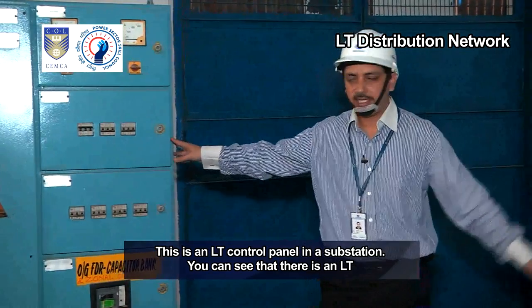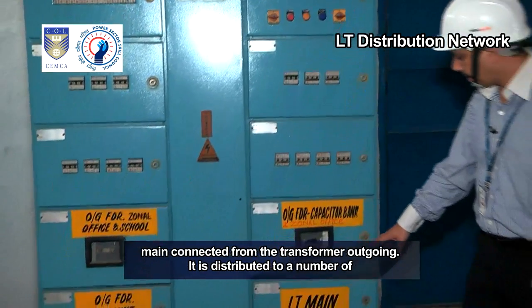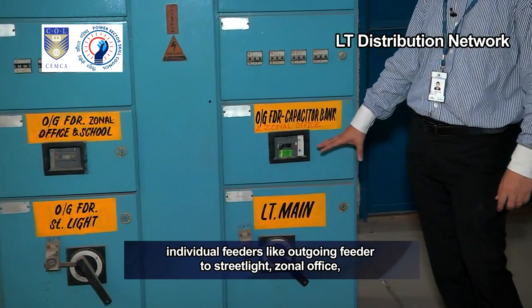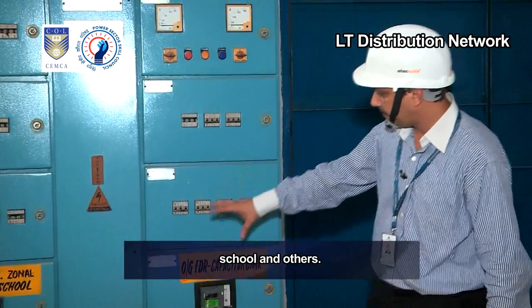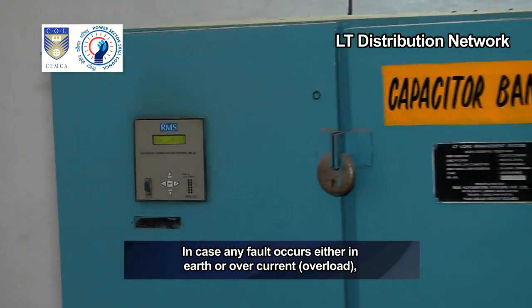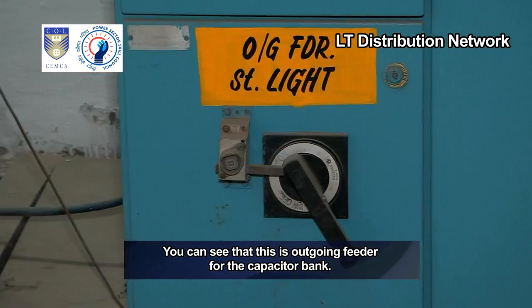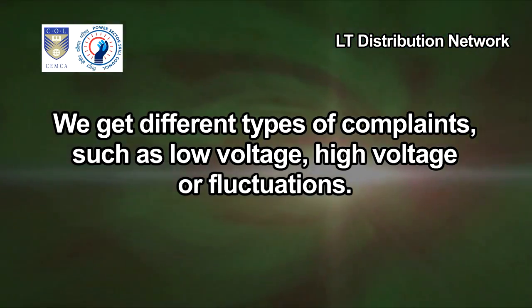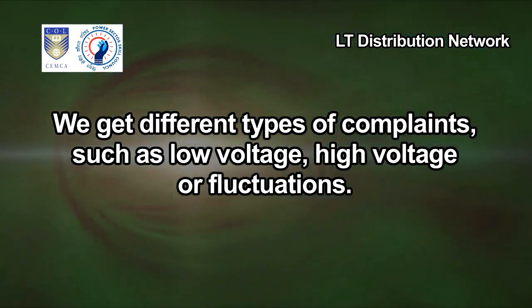This is an LT control panel in a substation. You can see that there is an LT main connected from the transformer outgoing. It is distributed to a number of individual feeders like outgoing feeder to street light, zonal office, school, and others. In case any fault occurs either in earth or overcurrent overload, the individual feeder gets tripped. You can see that this is outgoing feeder for the capacitor bank. It controls the voltage regulation of the transformer. We get different types of complaints such as low voltage, high voltage or fluctuations.